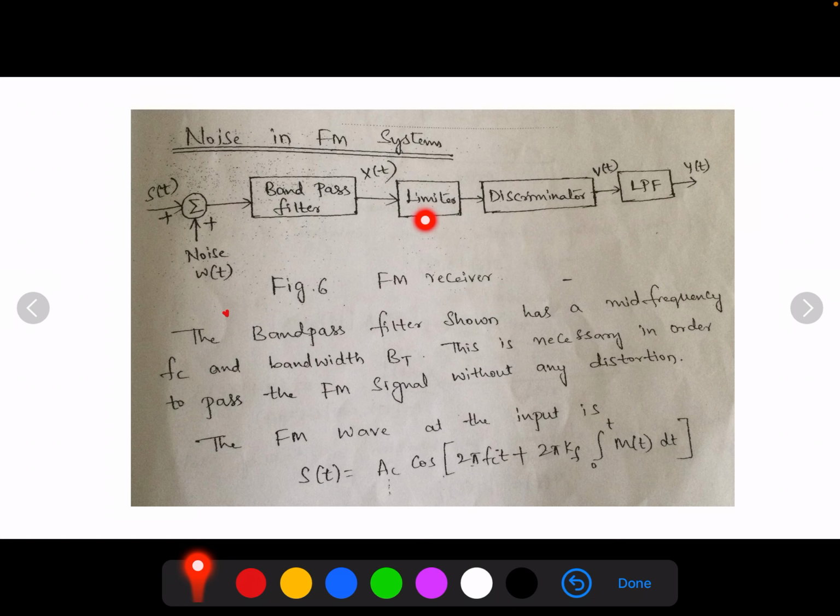It is used to remove any amplitude variations by clipping the modulated wave at the filtered output almost to the zero axis. The resulting rectangular wave is then rounded off by another band pass filter that is an integral part of the limiter, thereby suppressing any harmonics of the carrier frequency. Thus the filter output is again a sinusoidal wave with an amplitude practically independent of the carrier amplitude at the receiver input.